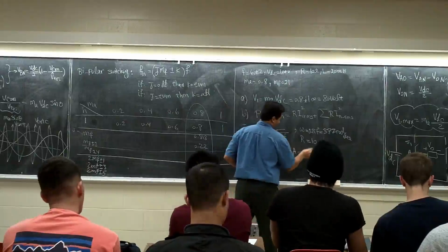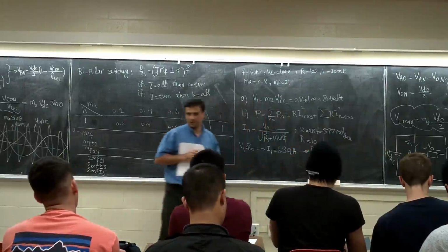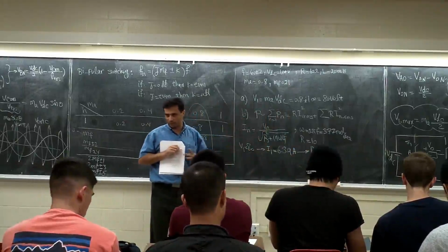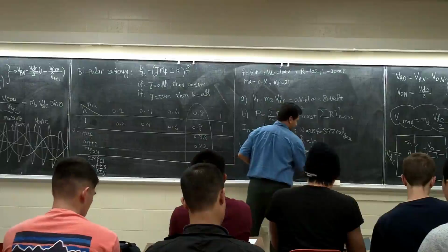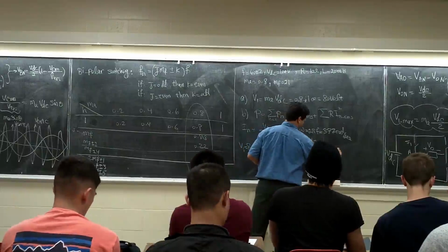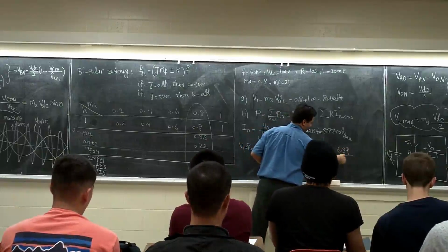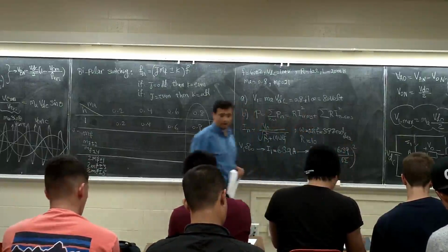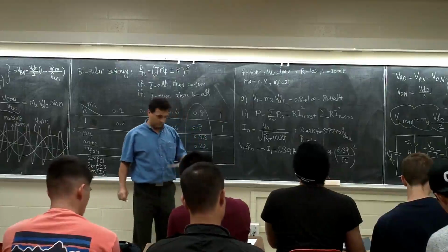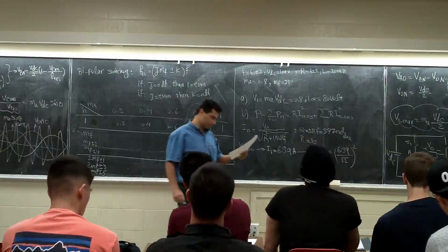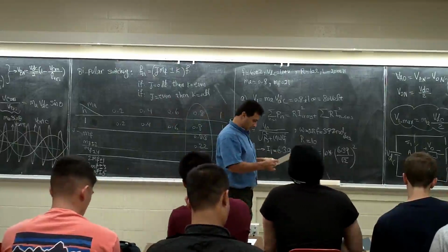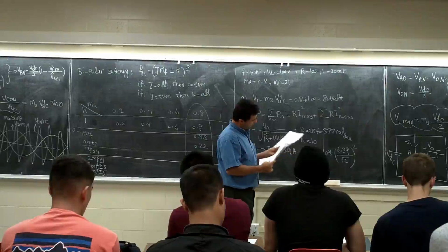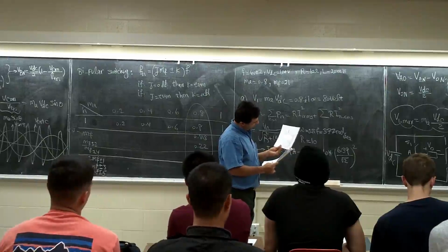So how much is the P1? R times the RMS value of this current to the power of 2, right? It is going to be 10 times 6.39. This is the maximum value, right? I should divide it by square root of 2, to the power of 2. So if you calculate this one, it is going to be 204.